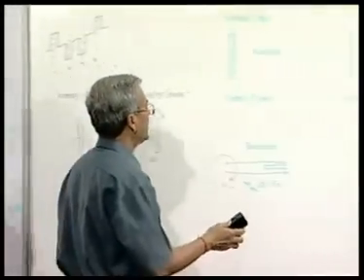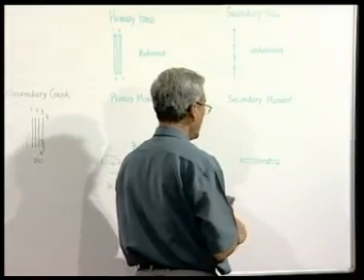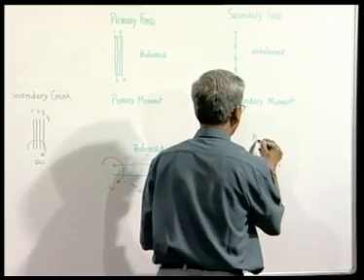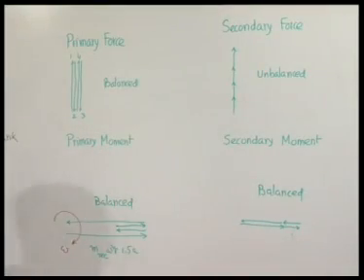So, overall there is an improvement, because earlier the secondary forces were unbalanced and the primary moment was unbalanced. Just by changing the firing order, we have achieved total primary balance and only the secondary force unbalance. So, now I think this sends the message that firing order is very important, and one can take up the case of 6 cylinder engines with 4 stroke cycle, and the crank arrangements,